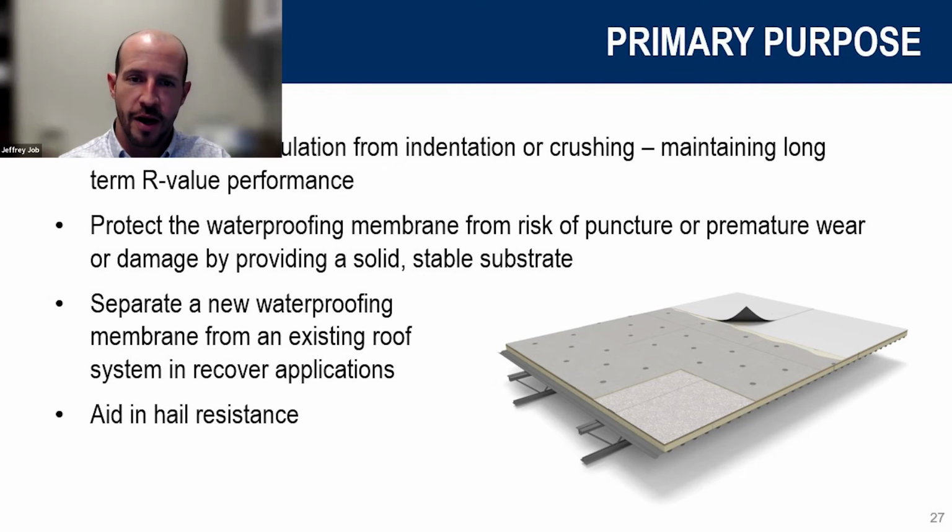100%. And just to add to that, I think fire resistance is another one that we didn't really speak to specific to coverboards. Gyp coverboards and coated glass face coverboards do have better fire performance than some of the other ones. It could also be, depending on the type of membrane you're putting down and the insulation you have below,